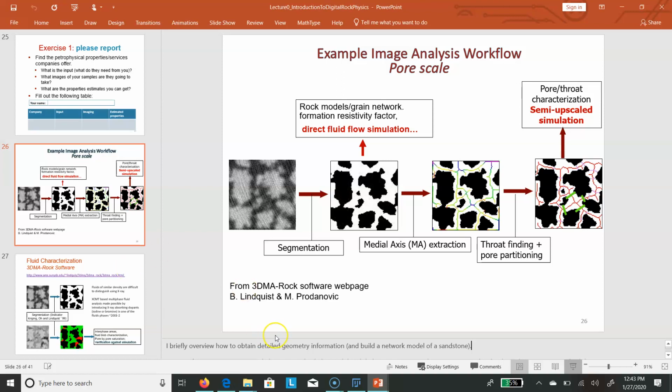This is the tomographic view of half of my PhD thesis. I was analyzing experiments of fractional flow through that polyethylene core. You can see basically a quarter of it here. You can see ring artifacts that are pretty prominent close to the center. There were actually 14 of them in the view, but here there's just some of them. So after injecting 0.5 pore volume of water, you get water that displaced some of the oil. This is still oil, this is polyethylene. Then you keep increasing pore volumes of water, injecting more and more.